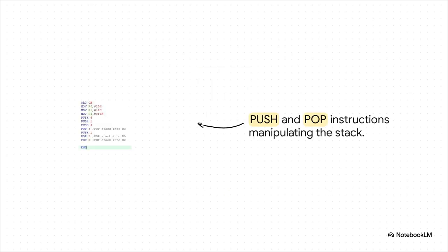Here's where it gets really interesting. When we use push and pop instructions, we're actually stashing our worker's data temporarily on the stack. And where exactly is this stack? Well, by default, the 8051 squeezes the stack right into register bank 1, sitting directly on top of our default bank 0. It is just such a beautifully efficient use of some very tight real estate.